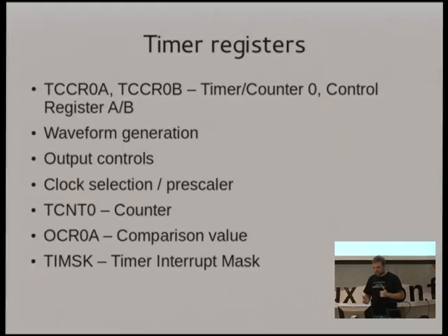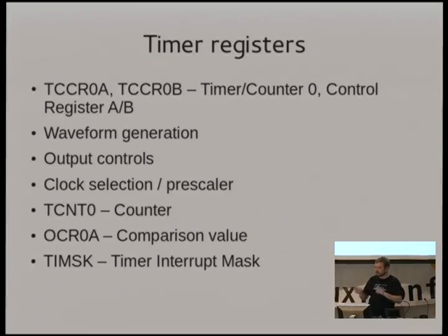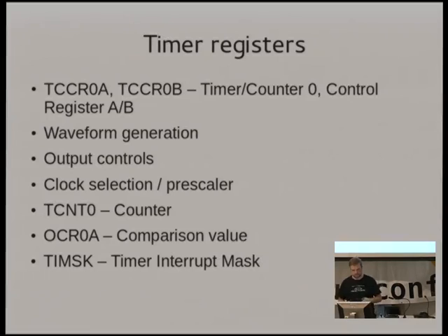The prescaler is because, if you're running on an 8 megahertz machine, even if it's just tiny little chips, 8 megahertz, you don't want to count necessarily to 65,535 one per clock cycle, because that's really, really fast, right? So maybe you only want to do it every 1,024 clock cycles. So there's a series of prescalers which basically just divide the clock by that speed and let you slow down that counting. Between choosing the overflow or comparison values and choosing a prescaler, you can actually pretty closely map to most real-world times that you might care about.